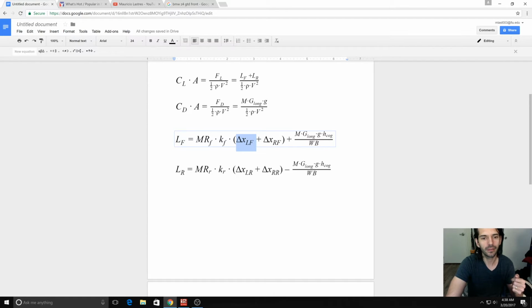So that's weight transfer, and you can see how it's actually made up of, in this case, two terms. There is also another term for unsprung mass. There's a weight transfer of the sprung mass, there's weight transfer for the unsprung mass, and the geometric weight transfer, and they are all added together. Two of those are instantaneous. One of them is directly proportional to the amount of suspension travel. Very important.